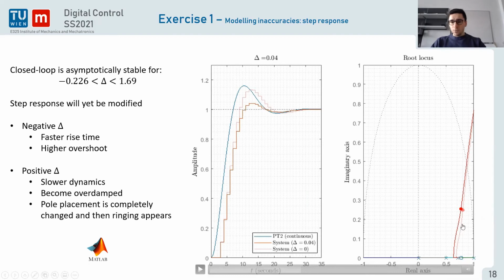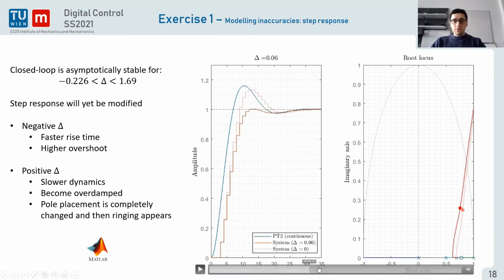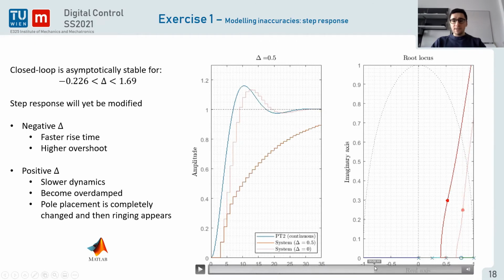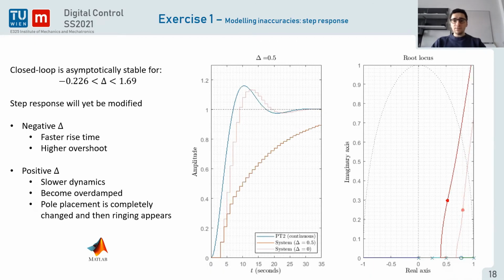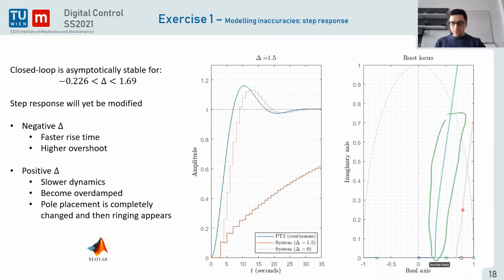And you can see how the closed loop poles I was looking for are also changed. And in the same way, if I increase it too much, I've got something that is completely damped at one point, there's no oscillations left. And after quite some while, you can see on the root locus that there's not even a conjugate pair of poles. So you can see that here, exactly here, there are no more poles here. So that means that all my poles are on the real axis in this case. And eventually one pole, this one I was talking about beforehand, is moving towards -1.